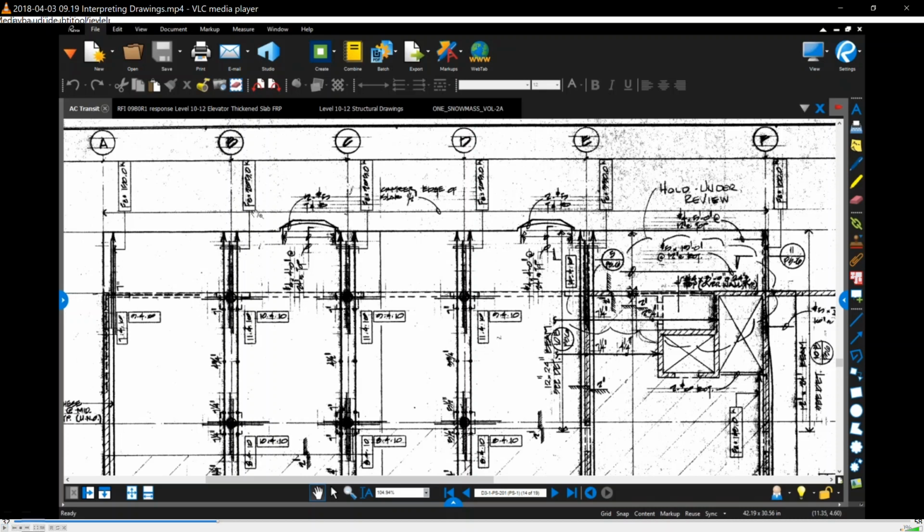So did you guys understand post-tension slab? This is a two-way slab, or two-way plate, as it's called. The banded cables act like beams, and the uniform cables act like a one-way slab, sort of. So that's how you can relate the two together.